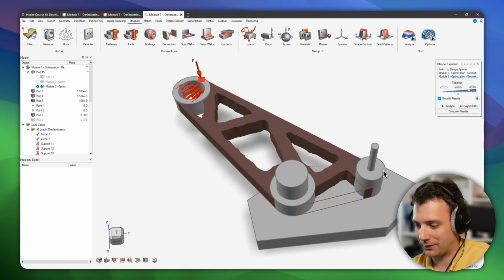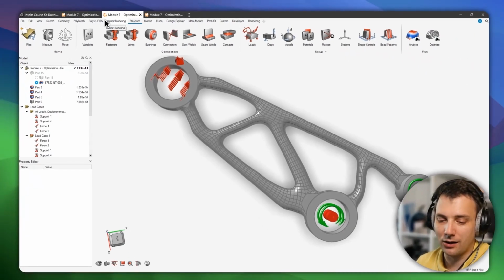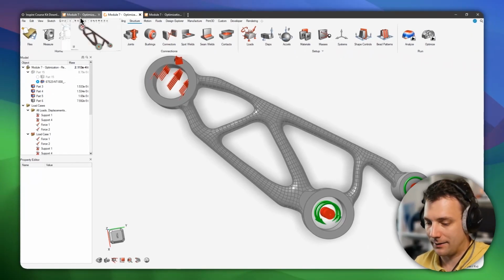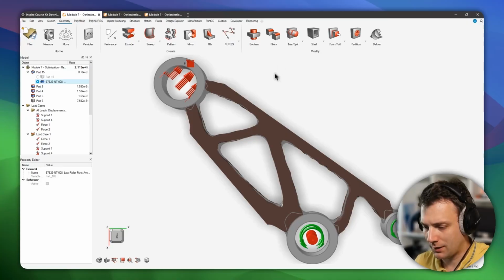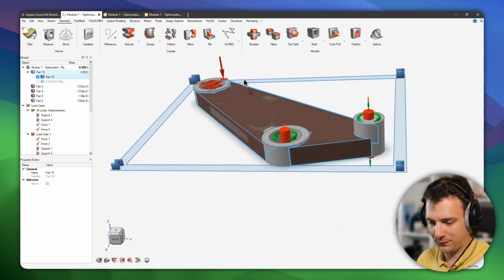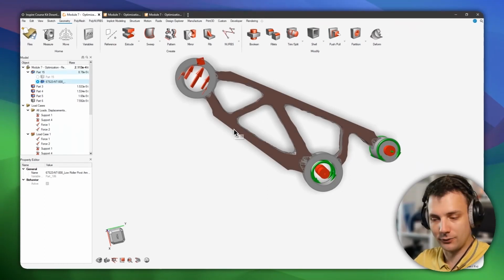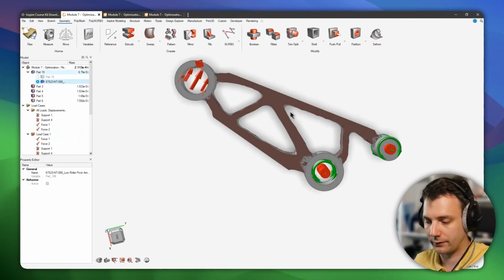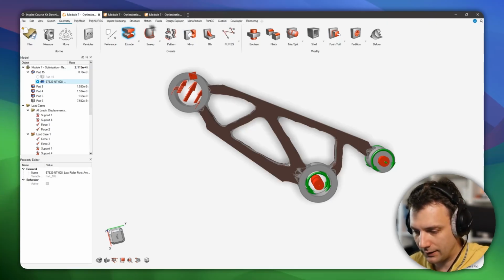Check topology optimization out. There's a lot more topics we could cover, for example different shape controls. I can cover them briefly, but you can watch a lot of other videos on my channel if you would like to get more education on topology optimization. Just briefly to cover it, what we did here was a topology optimization with an extrusion constraint. That means that this part which comes out has more or less a constant cross section over the set direction or thickness.